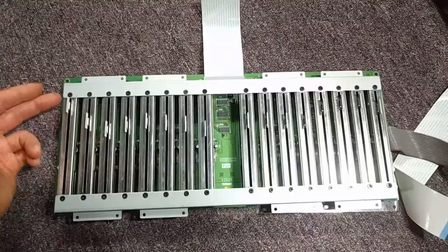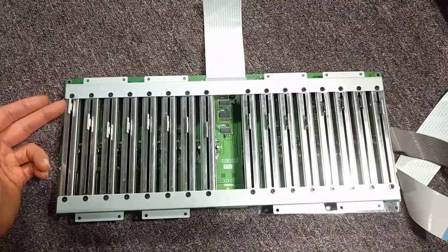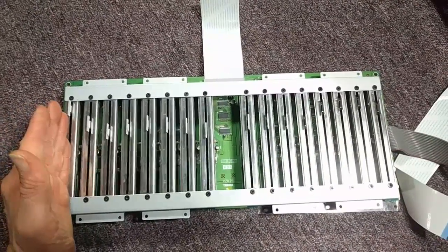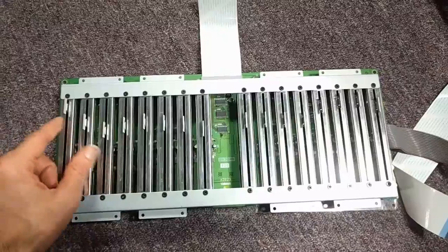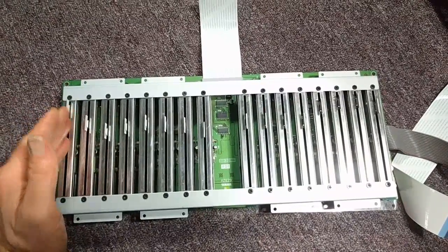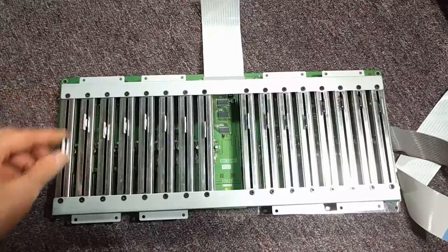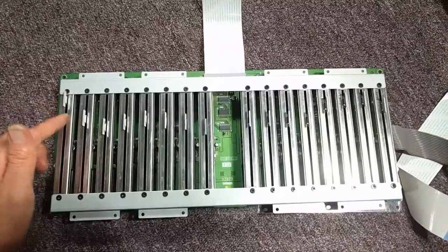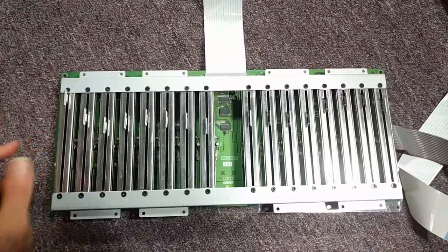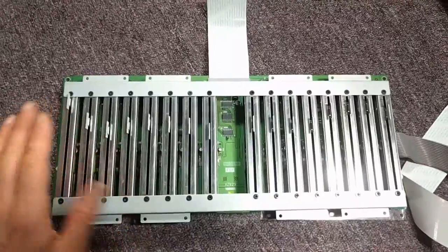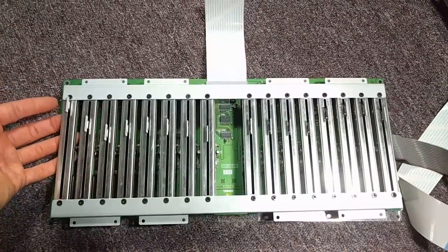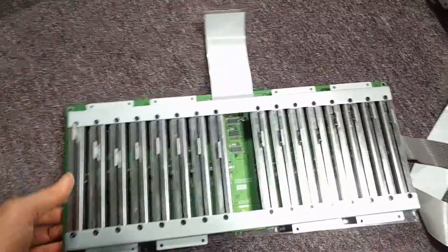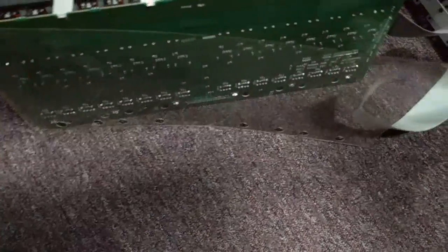And so what I ended up having to do was very, very gently drilling down the notches that are already present in the PCB, so it can be shifted ever so slightly over. That could just be the teeth being damaged as well, so I tried to shift those a little bit too. But it's such a precise system that you really have to make sure that it's all working. I actually thought there were spots in the resistive track that were damaged. Not the case. Everything was fine, which was good because it meant I didn't have to replace it and wait for parts. I could actually repair it, but it was not fun. And gosh, I think next time I might just replace it, honestly.